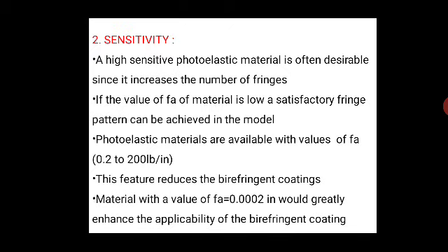The second property is sensitivity. Everyone knows sensitivity from various applications: how does it sense depending upon the input load, and what is the output with respect to the input? High sensitivity in photoelastic materials is often desirable since it increases the number of fringes which can be observed in the model.